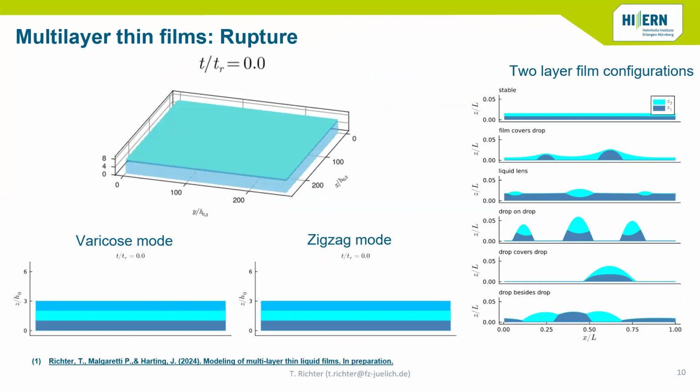In vertical direction, none at all. We're describing it by a height field. Is that what you're meaning? How large the resolution is in this direction? We're not resolving this direction. The whole idea is to describe liquid films by their height or thickness, and therefore the only discretization we have is in this direction, and in this direction it's continuous. So we have a float value of film height in that position.